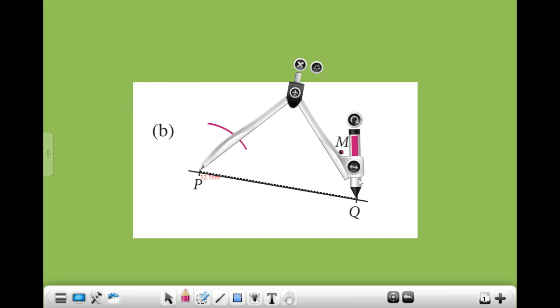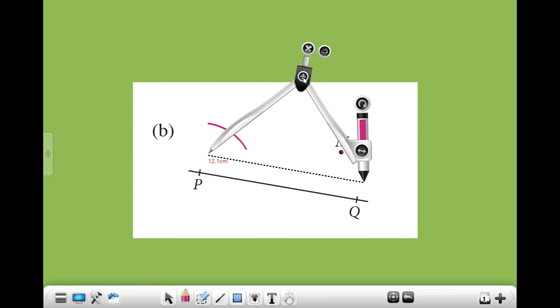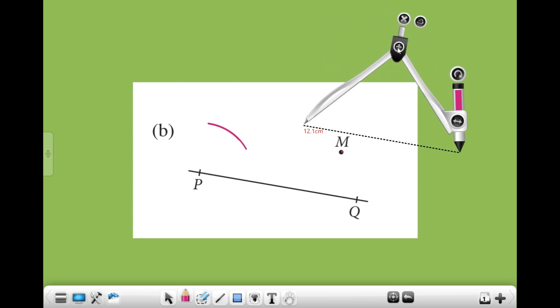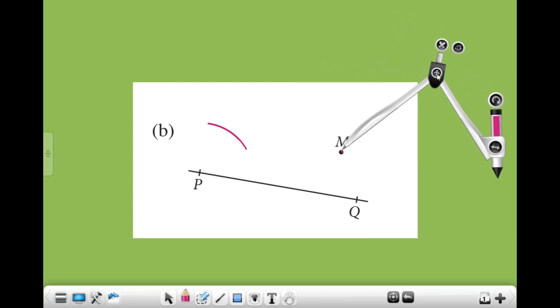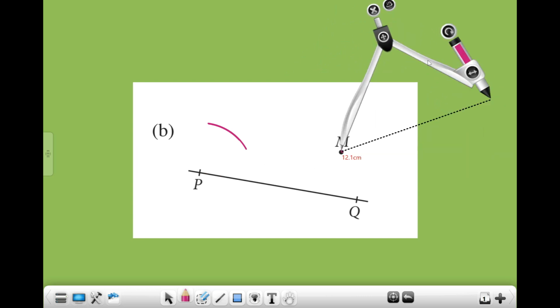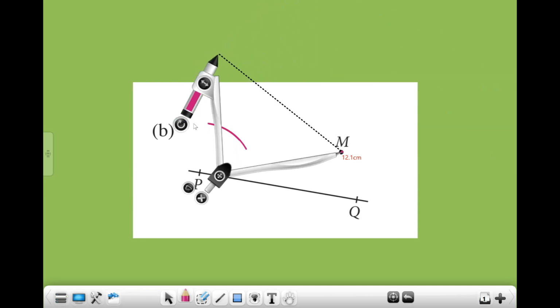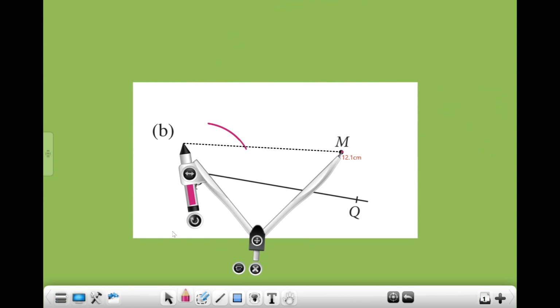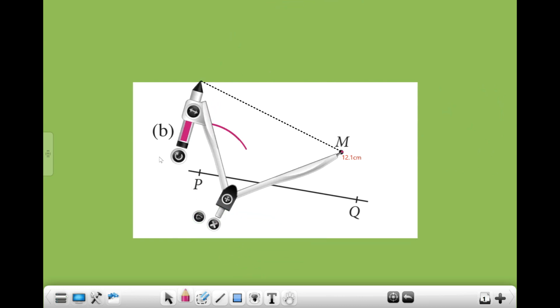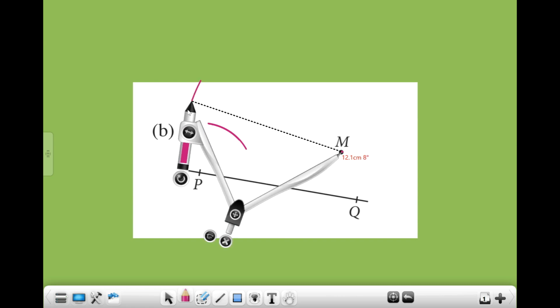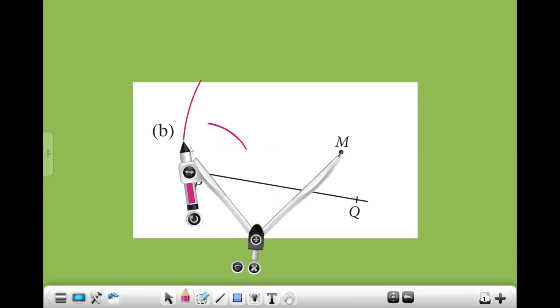Yes. Okay, so remove it. Put the sharp end on top of point M. Are you ready? Make sure you don't alter the size, so you turn your compasses. Mine have to turn this way, there's no choice. Yours can turn right hand side or left hand side. Oh, you see mine, it doesn't cut through. Okay, it doesn't matter. I draw my line first. Draw the arc first. If yours also like mine over here, it doesn't cut through, you can't get the intersecting point, doesn't matter, don't worry. Just extend it first. Those who got your line, you can proceed to use your ruler.